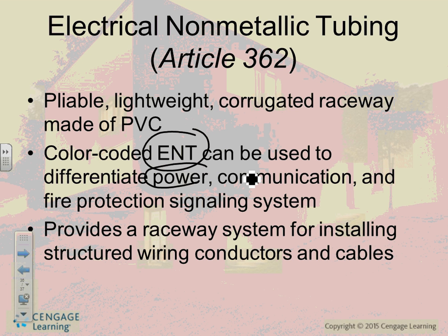You bend this one? They got pre-made then. Yeah, for bending. Yeah, they're bending these guys. For these, they have hand benders and machines. For this guy, like you said, they use a blanket or a heater or a box. So you heat it, and you have to make sure you put your gloves on, and then you bend it to